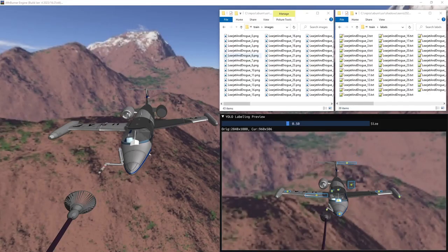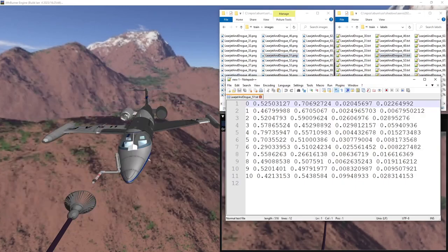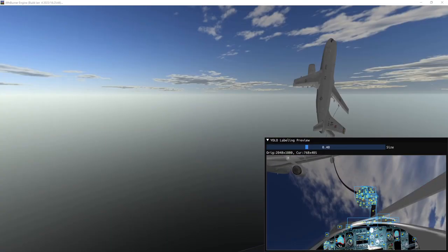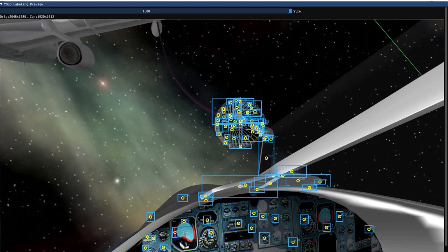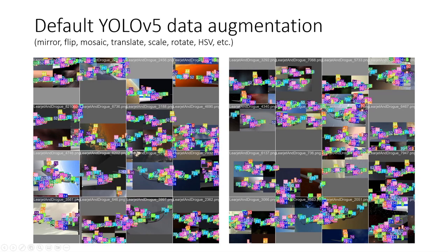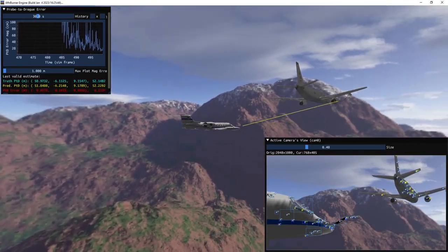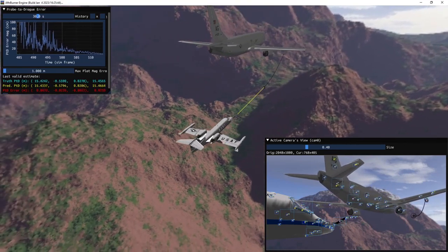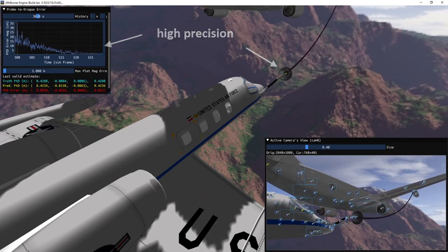This automated process allows us to generate approximately 30,000 precise, error-free labeled images an hour. In addition to bounding box corrections, we augment approaches with various backgrounds, lighting effects, orientations, and occlusions. This, paired with default YOLO v5 augmentations, ultimately leads to better generalization and model performance. After training our models from labeled images with bounding box corrections applied, we observed YOLO was able to find 2D image points with enough precision to produce highly accurate probe-to-drogue vectors.